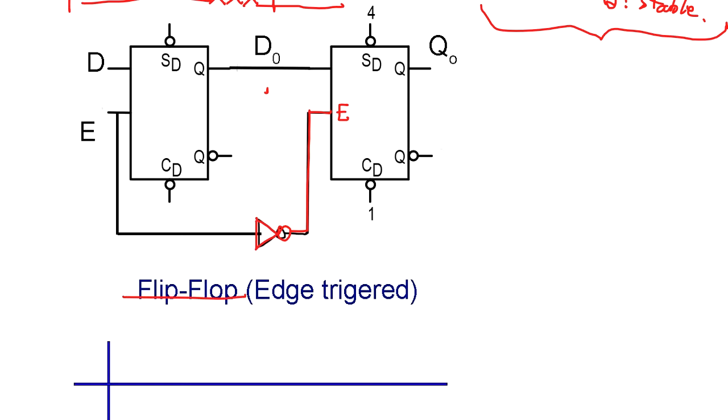The first half cycle, you take in data and latch up here, right? And since it's inverted, the next half cycle starts this moment, you transfer this into this. So data is transferred to be here. Then next half cycle, data starts changing here. But since output is controlled by the second latch, output will be stable. So I'll show you in the timing diagram.